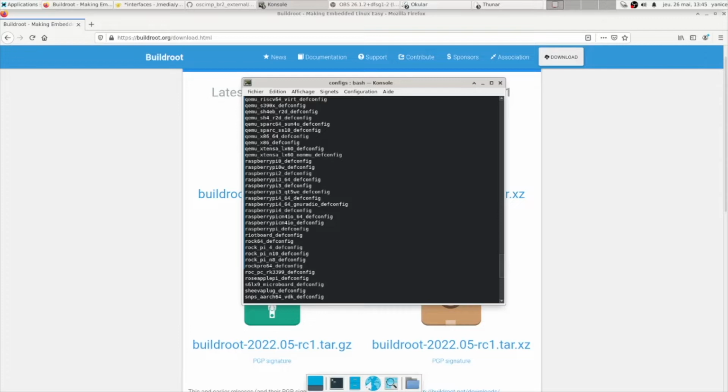Then we place Buildroot in the main directory of your computer. Thanks to the package manager, we can install GNU Radio and Osmo SDR packages in our Buildroot. We don't forget to git clone our teacher's GitHub folder, which will allow us to get the right settings for GNU Radio and place it in the configs folder of Buildroot.